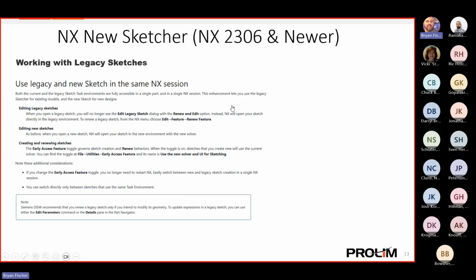Whoops, I'm sorry. I did not mean to hit play on that. That's my bad. So within here, this is the information that came directly from that link for the customer within the help for What's New. It talks about editing a new sketch, and the recommendation still is, if it's just a dimensional change, leave it in the legacy sketch. There may be wave geometry or you may have an expression that's used somewhere else. I would recommend leaving it in the legacy sketch unless you have to make a model change.